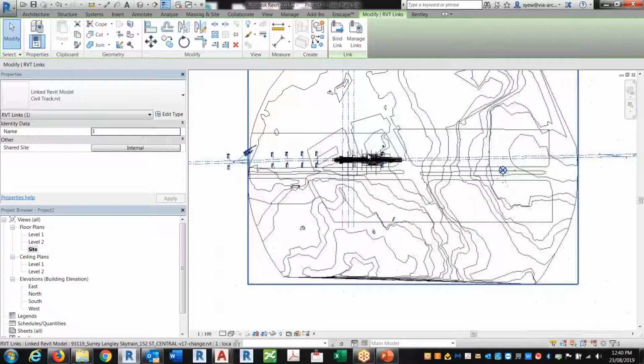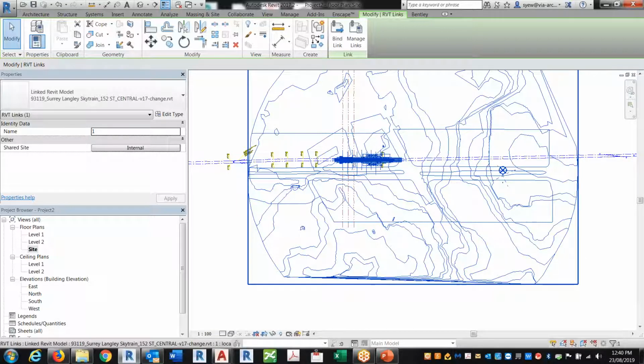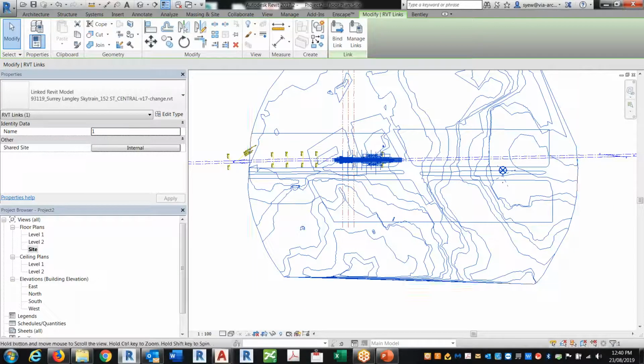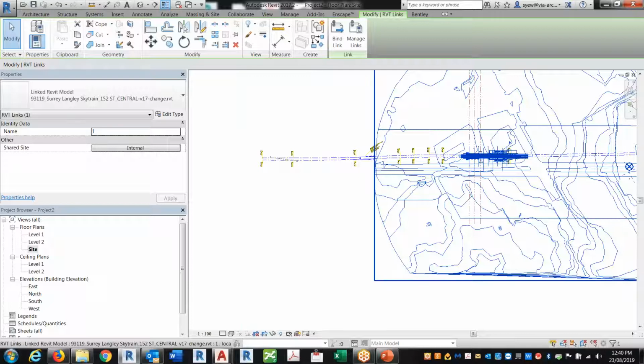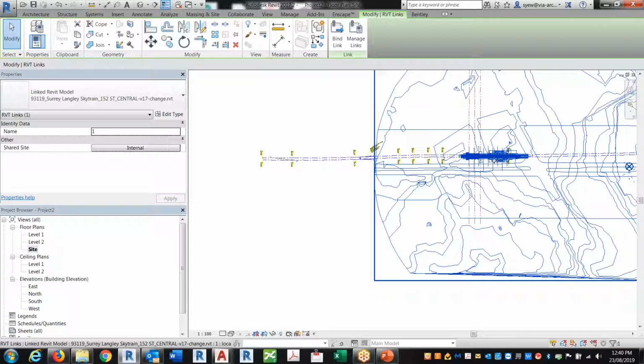Once you've done that and acquired coordinates from this, now you're set. So next time when you have a new file, you link in the Revit file here, and you just hit acquire coordinates. The origin points can be the same, it doesn't matter where it is. I always maintain the origin point to be the same. It's like AutoCAD, you just say 0,0, that's my 0,0. Acquire coordinates. Next time when you have different coordinates, like this one and that one have the same coordinates, then this one will position the coordinates the same as this particular file, automatically.